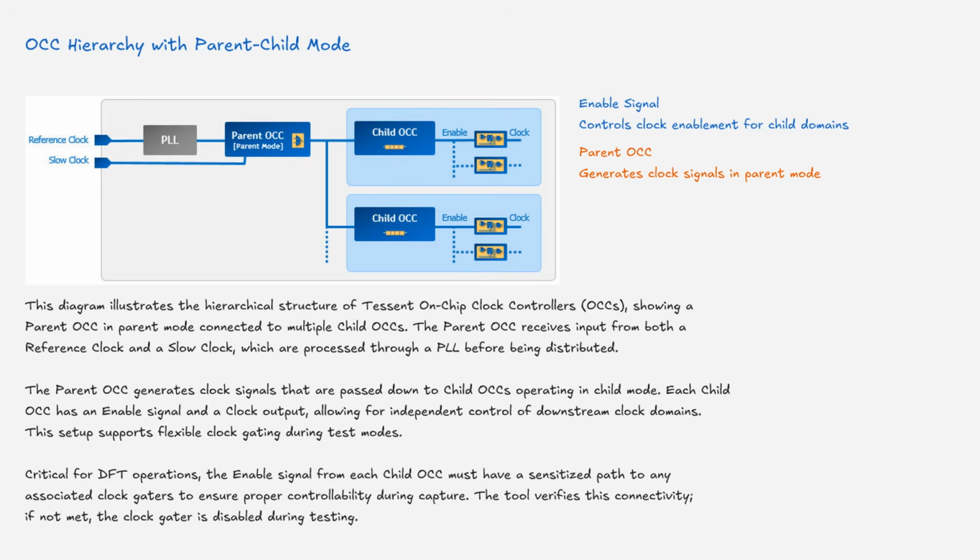Critical for DFT operations, the enable signal from each child OCC must have a sensitized path to any associated clock gators to ensure proper controllability during capture. The tool verifies this connectivity. If not met, the clock gator is disabled during testing.